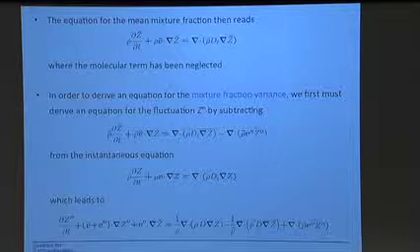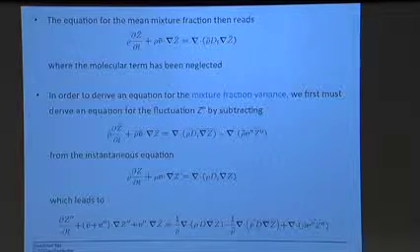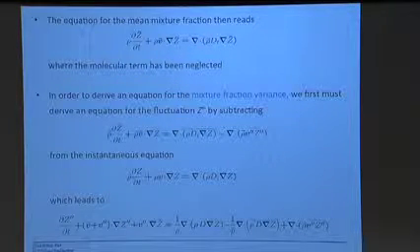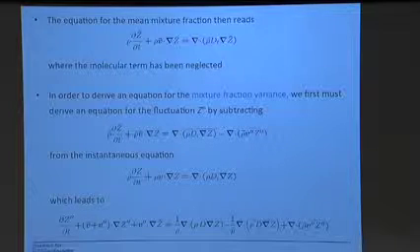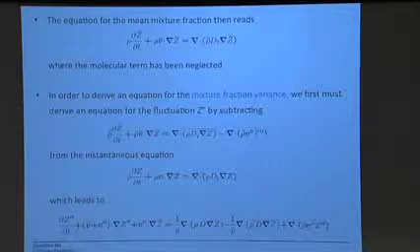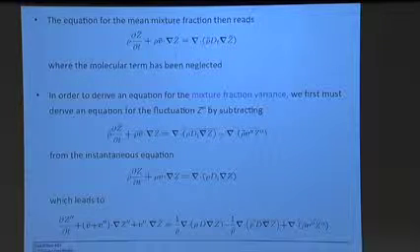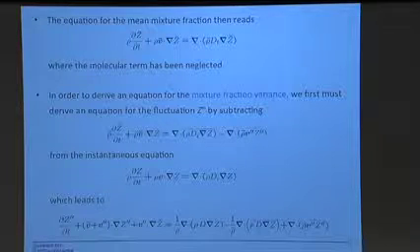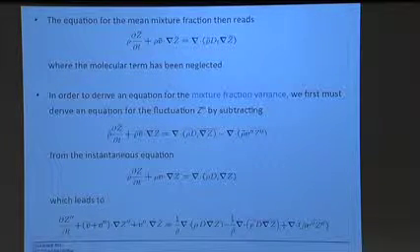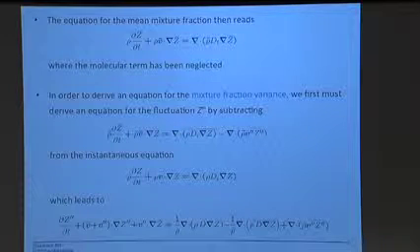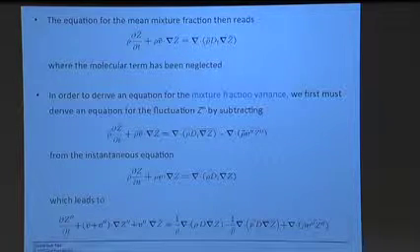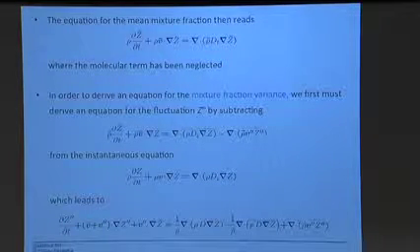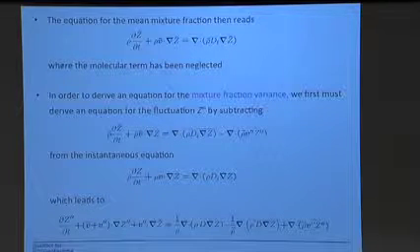Okay? Now, turns out, just like to describe turbulence, we need the mean and the turbulent fluctuation. The turbulent fluctuation of the velocity was characterized with what quantity? With the turbulent kinetic energy. Just like we need the information about the mean and the fluctuation, also for the scalar we need information about the mean and the fluctuation. And later on, when we talk about non-premixed combustion, you will see why we need that information. But we can also derive an equation for the so-called scalar variance.